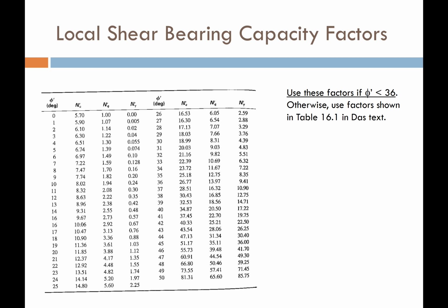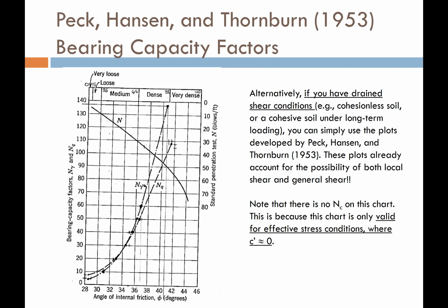I'm just going to give these values back to you. These aren't in your Das textbook, but I'm giving them to you here. So if you're doing bearing capacity design and you have the case of local shear failure, use these bearing capacity factors instead.